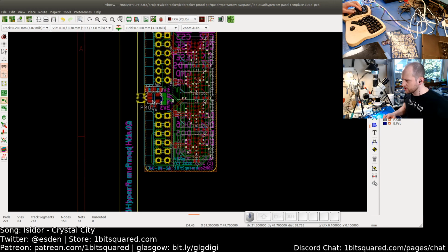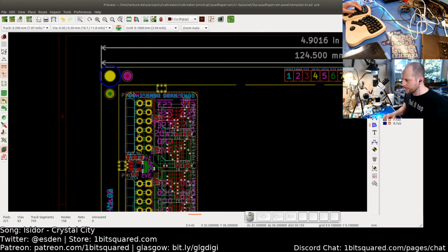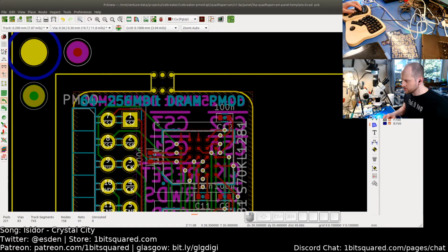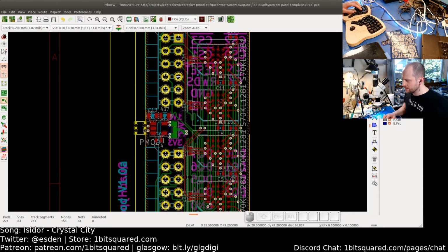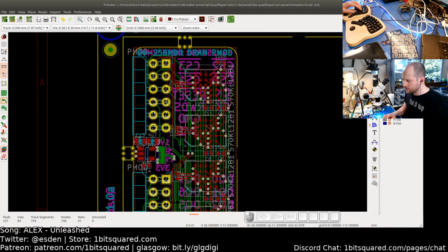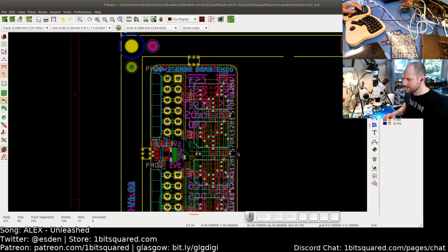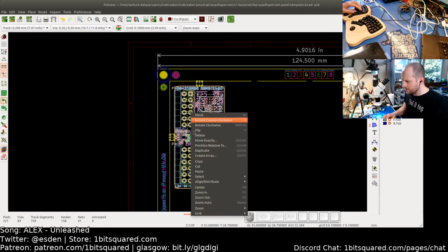So what we will do is import this board, move it to this position, cut the notch in the top and the side, use the array tool to copy these accurately over from top to bottom, from left to right, make these notches, and then select this whole thing and go in the array tool.